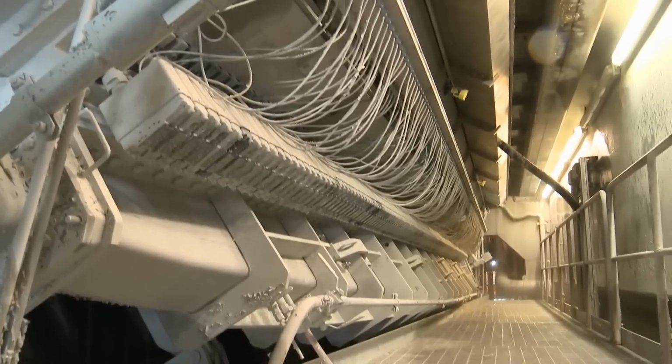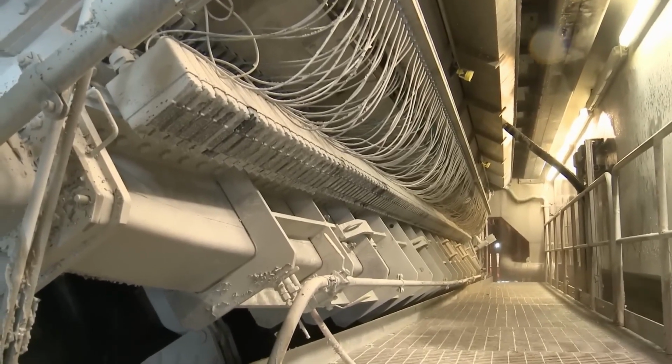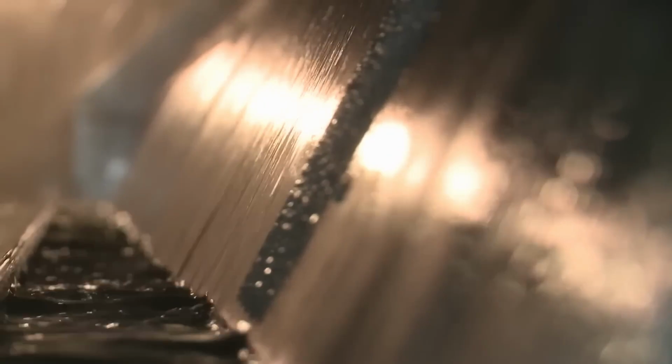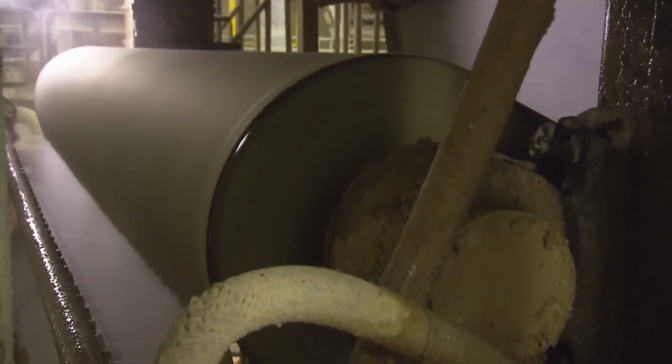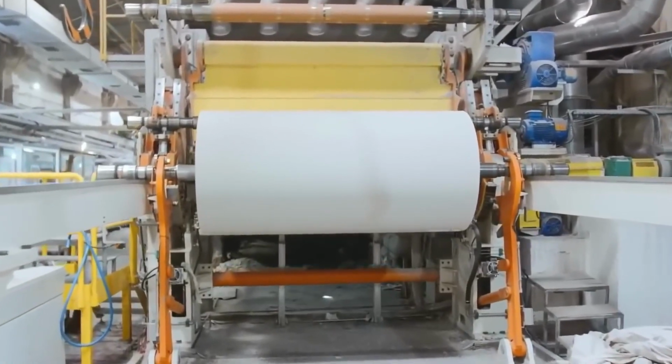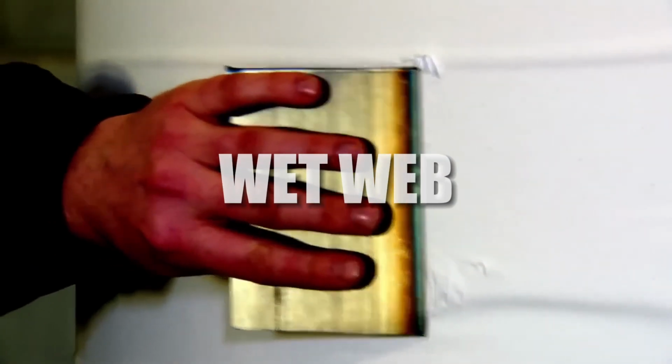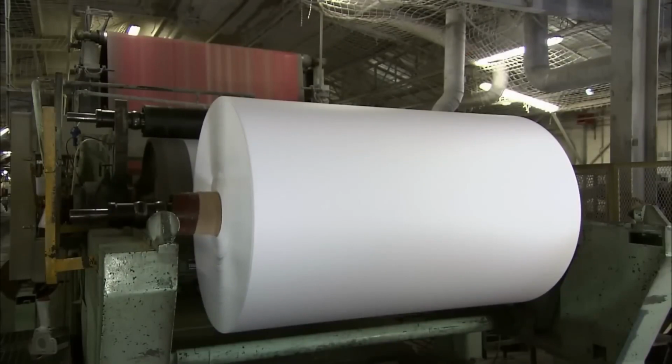As the pulp mixture progresses, the water drains away, facilitated by vacuum boxes and other drainage features that help control the consistency of the pulp and the thickness of the paper sheet. Next, the wet sheet of paper passes through a series of press rollers that further extract the water, increasing the density of the paper. This pressed sheet, now referred to as the wet web, still contains a significant amount of water and is guided through a series of heated rollers, or drying section, to remove the remaining water.